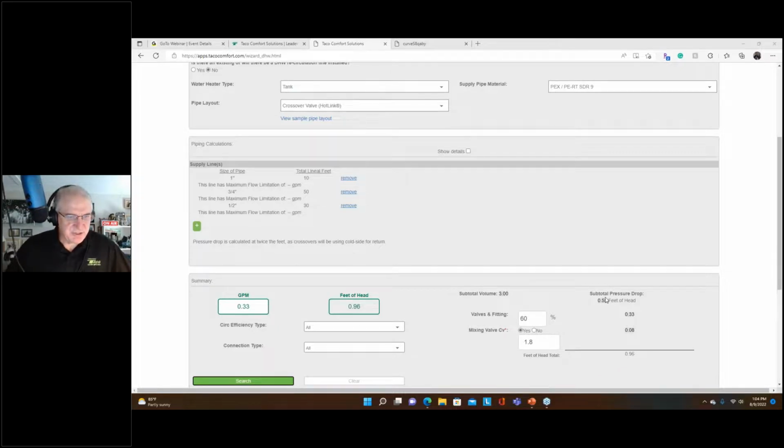Where does the circulator suck water from? First, the circulators don't suck water; they recirculate. It's different. It doesn't suck anything. It just recirculates. What it's doing is it's deadheading. It's simply not moving any water at all through that loop. So it's pressurized and everything. It's just simply spinning and not moving any water. It's called deadheading.